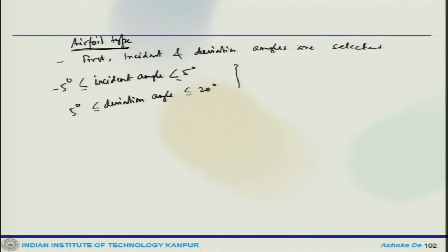So, the nature and type of blading depends on the application, and so this is one of the important aspects, application and Mach number. That means whether it is a subsonic range, high subsonic range, transonic range or supersonic range. So, that will determine this, because once you go to transonic or supersonic range, there would be shock waves, and that will have some loading on the frontal stages.